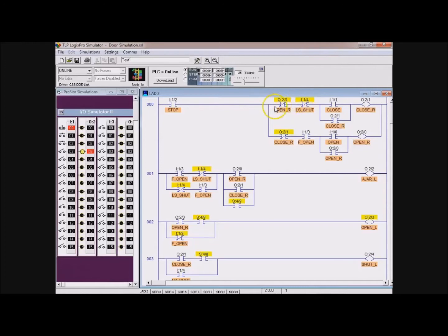And what's nice about a PLC is it shows me what's already true. You see that? It says this button right here is true. So if I come over and press this button right here, you see the yellow light come on? What we can do with a PLC that's really hard to do in motor controls is it helps us troubleshoot. So this is telling me that the PLC is seeing that input right there.